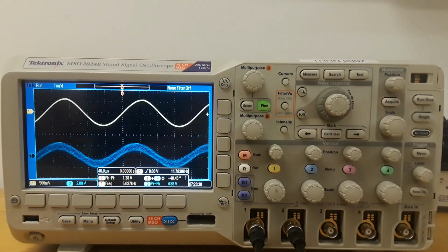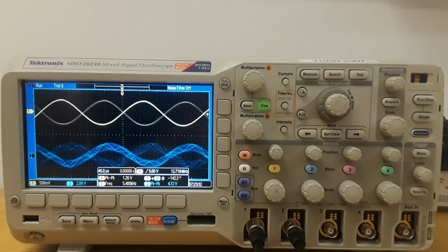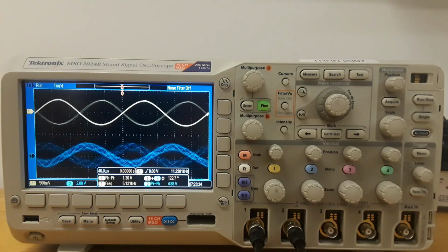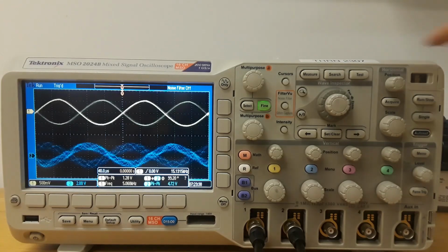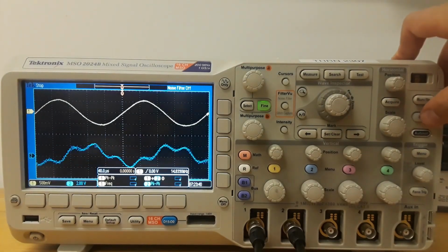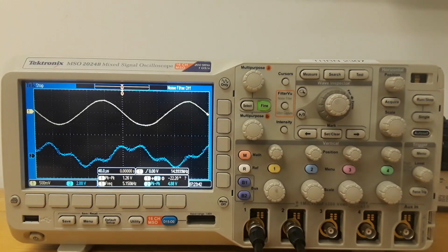And here at 5 kilohertz, well, same story again. We've got a lot of noise, but we've still got a recognizable 5 kilohertz signal on that output. When we hit single, now we can maybe even get a little bit of an idea of what's going on. It's not perfect, but we can absolutely see that we have some parts where it seems to be staying flat before it jumps back to the next lower signal. And that's exactly what we expected to see, given that we're doing a zero order hold.